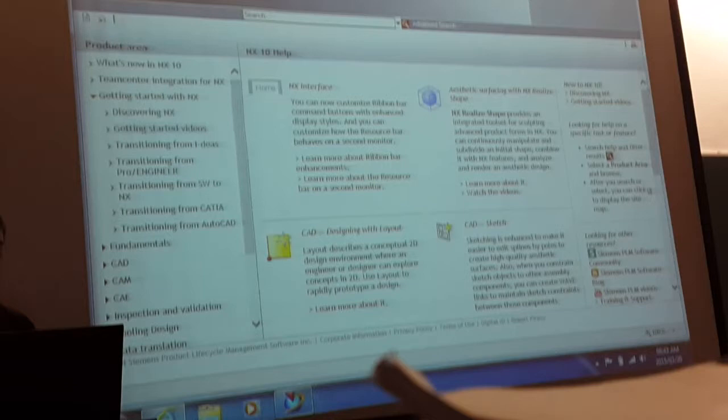Right, and it asks you for which plane you want to be sketching on. So you can look at the data coordinate system, right, and select the plane that you want. So I would put it on the YZ plane for argument's sake. Right, the quick pick, which is a feature of NX. Basically, if you select something and your selection is ambiguous, it comes up with options associated with that ambiguous selection. You can see that what is selected automatically is the Z plane. We don't want that. It has given us the YZ plane option, so we can select that. Okay, we've selected our plane, we said OK,